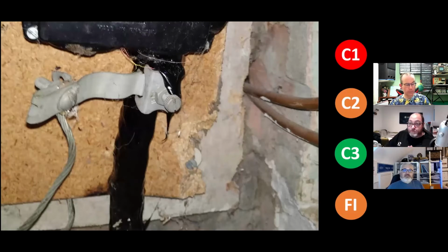As you've rightly said, Dave, if you're ever really going to do any purist load monitoring of anything, you need to spend a week, and it needs to be done in the coldest weeks of the year to really understand what the maximum demand on that actual installation is. Oh, yeah. You need to be there when it's under the most stress. So if you're an electrical contractor and you want to make loads of money, Christmas time load monitoring, best time.